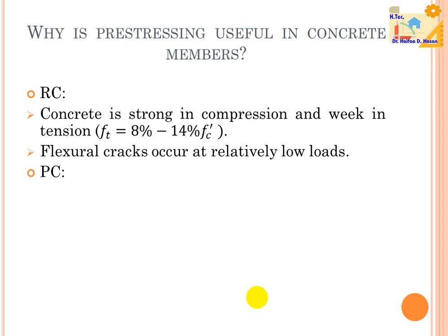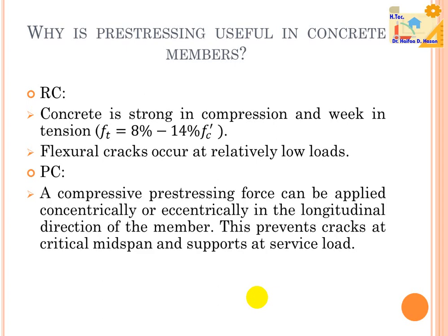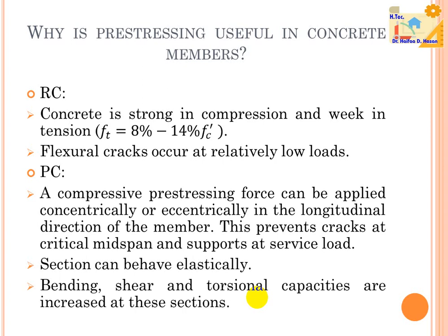In a pre-stressed concrete member, a compressive pre-stressing force can be applied concentrically or eccentrically in the longitudinal direction of the member. This prevents cracks at critical midspan and supports a service load. The section can behave elastically. Bending, shear, and torsional capacities are increased at these sections.